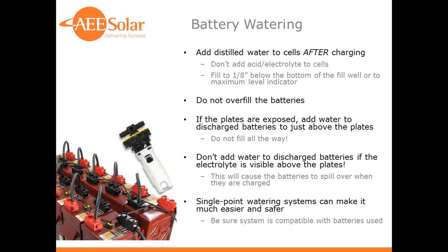Typically, you don't add any acid or electrolyte to battery cells. They come from the factory with the proper amount of acid in there, so we're just replenishing the water that's lost through electrolysis of the water and through evaporation. Certainly, if you were to, say, spill some electrolyte out of the battery, it might be appropriate to add some acid at that point, but that's a pretty rare situation. You don't really want to have an acid spill, so it's not something that hopefully will come up for you.